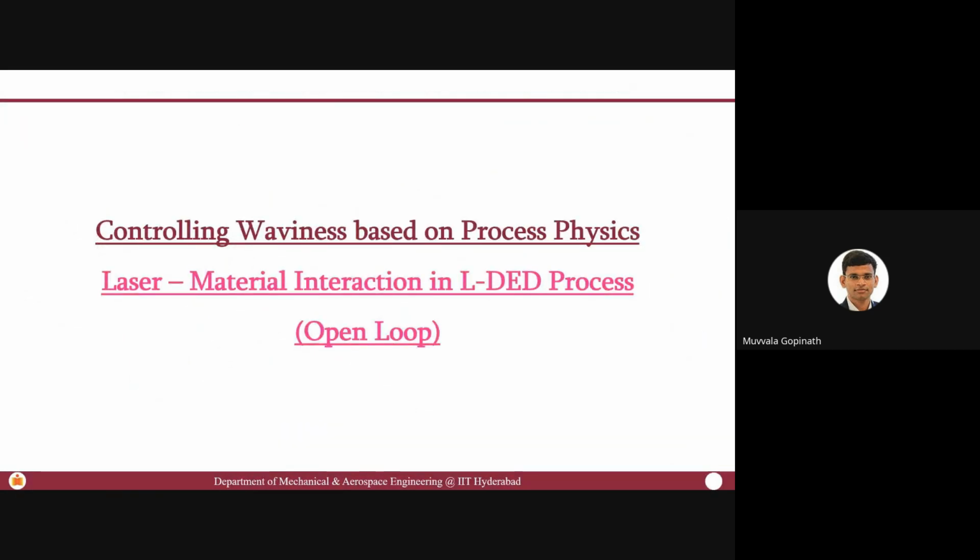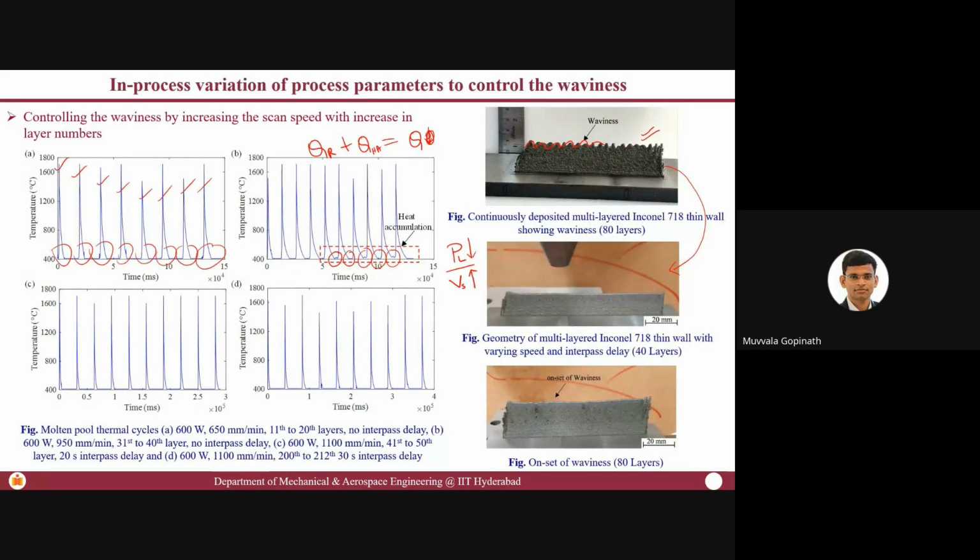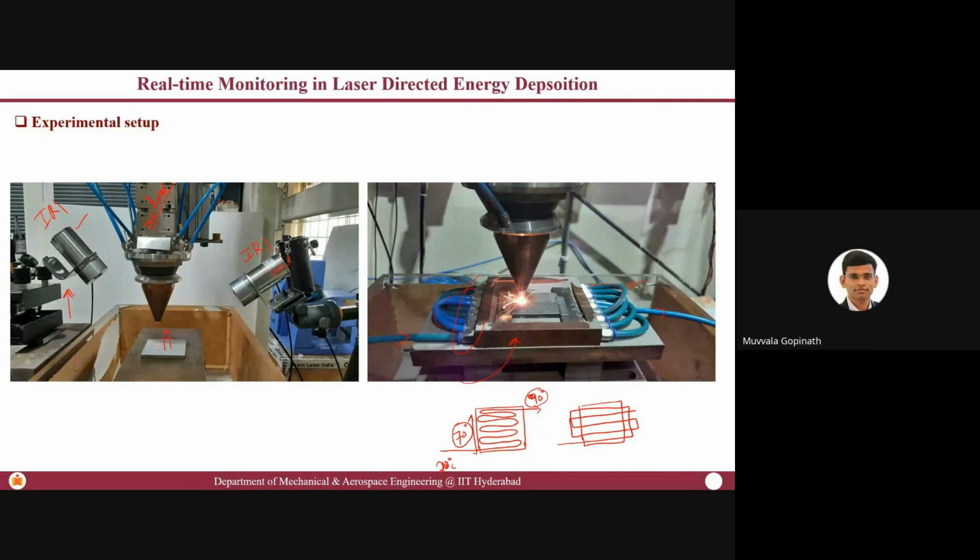Yes, Dr. Satyanarayan Reddy. Yes, sir. Actually, there's a water-cooled copper chill block which you use in directional solidification castings. So here also, if you incorporate the water-cooled chill block and vary the flow of water, so that you can increase or decrease the heat removal whenever you want by varying the water flow rate, do you think that might help to some extent, sir?